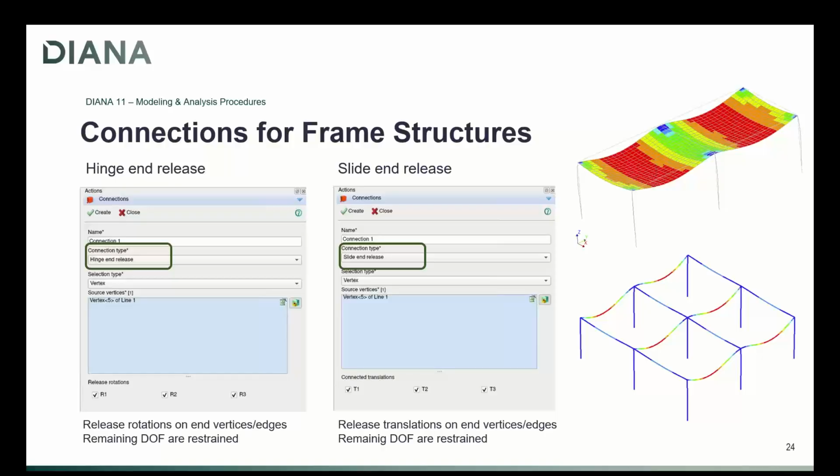The problem of that method is that if we have too many beams or shells connected at a point, then the tying condition becomes too complex, and sometimes we run into tying errors. And also, because it is more like a nodal approach, if one node is what we call hinge, then the whole connection becomes hinge. Even if we have 3 beams connecting in one point, then all 3 will become hinged.